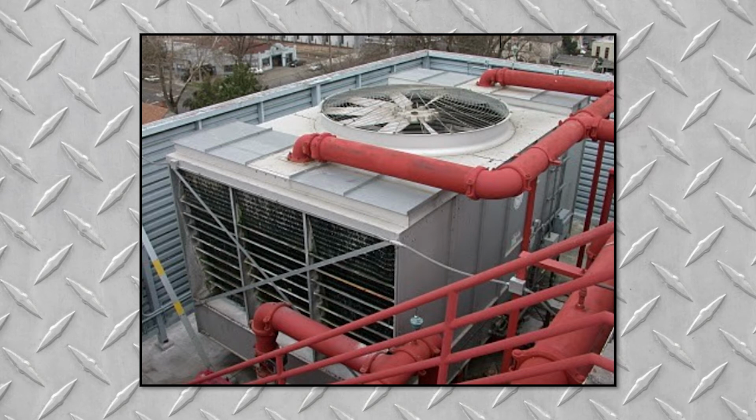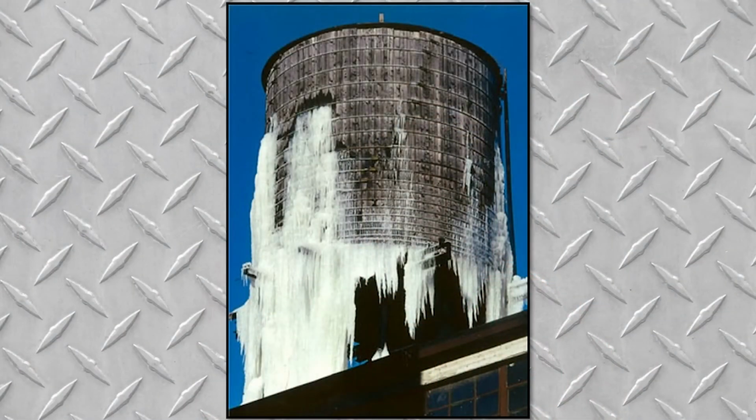Remember, the noise of the fan can be a problem if you have a roof-mounted cooling tower, but that shouldn't be a deal killer. Just work on making it quiet. Roofs can be great places for cooling towers. If you're in the kind of climate where you get freezing temperatures fairly often, you also have to worry a little bit about icing. But if this does begin to happen, you'll find your operator will most likely be putting antifreeze into the cooling water. Or in some cases, you operate the towers dry, giving up some of the wet bulb temperature benefits so you don't have to deal with the icing in the first place.